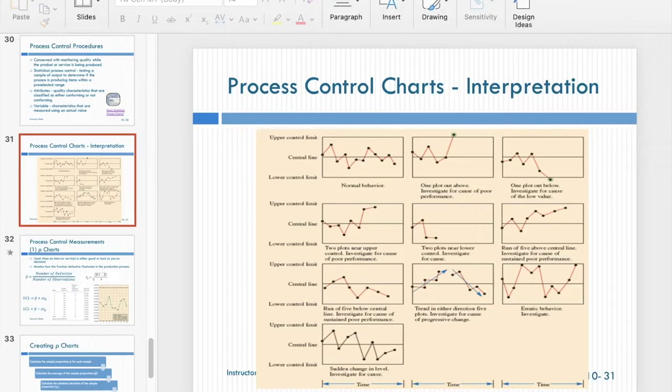If you look at the third plot, you see this dot is already below the lower control limit. It also shows some problem. So no matter whether it's the second one or the third one, you already have some warning. If you are an employee monitoring this whole process, you have to report to your manager that the quality control procedure already shows something abnormal. You may consider stopping your production process immediately, and try to figure out the reason.